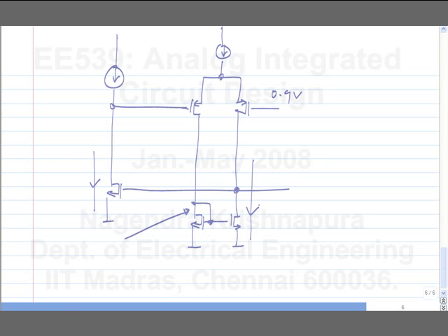Now the difference is, let's say you didn't make it to be the same. Let's say you had some difference between the quiescent current density of this and this. What happens is, this particular circuit, the one where you have a high DC gain, will have a high overall DC loop gain. So the effective systematic offset at the input will be smaller. So that's the effect of DC gain. Higher DC gain gives you higher precision.